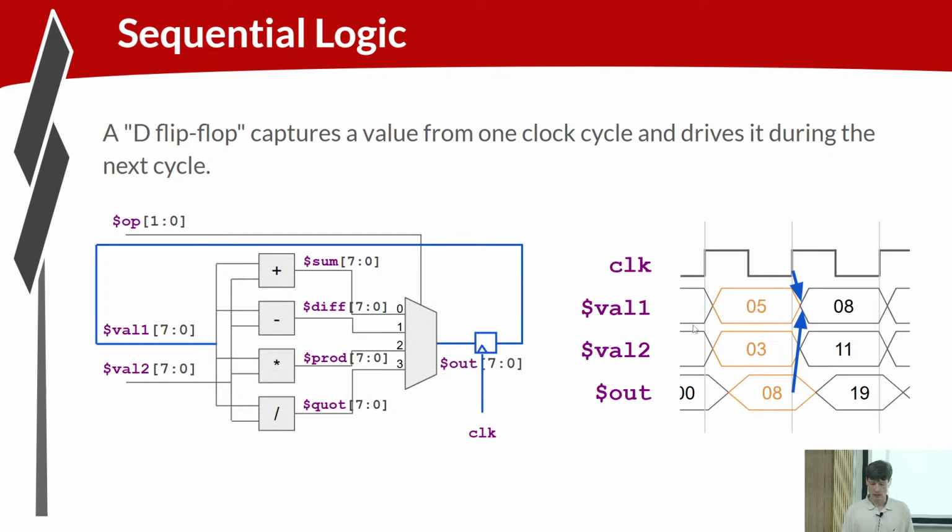So let's see. So in the waveform here, Val 1 and Val 2 perhaps are driven by a clock edge. Val 1 certainly is. It comes straight from the flip-flop. And let's say Val 2 also is driven out of a flip-flop. Those transitions will happen fairly immediately at the clock edge. The output's going to take time. The values have to propagate through.